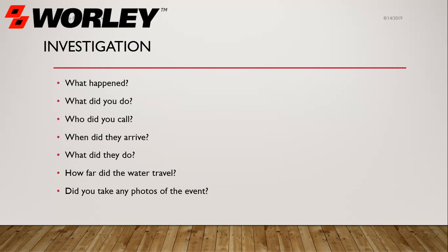If you talk to an insured and they said, well, I found the water on the floor, ask when was the last time they were in the room, and when did they come back? I went to bed, I woke up. So how long did you sleep? 4 hours? 14 hours? We need a timeline because this all impacts the way we would dry, or how long material has been exposed to moisture or water.